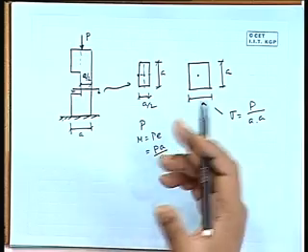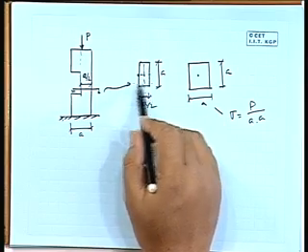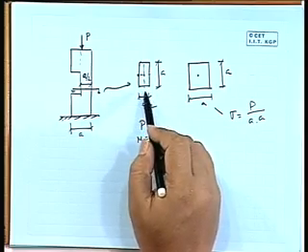So M Y by I, that part will work, right. So there will be one compressive part, that will be maximum, and the minimum part will be tensile here, because it is not within the 1/6 range of the core, right. So it is going to the extreme point, automatically this end will get tension.